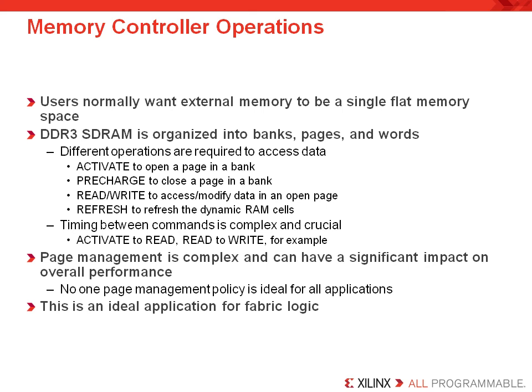So what is best is to use the IP for the memory controller as part of the memory interface generator. So that's our best solution. We've already got pre-optimized components that are going to take full advantage and allow you to build the memory controller you'd like. It's very challenging to try to do this on your own, but this performs the operation reorder for efficiency, and it's based on the Virtex 6 DDR3 memory controller. So our technology is proven. The controller itself operates at 233 megahertz even though the data rate is high. Now the MIG, or the memory interface generator, is included with the core generator as part of the ISE and the PlanAhead software, so it's included for free. The DDR3 core is also free.